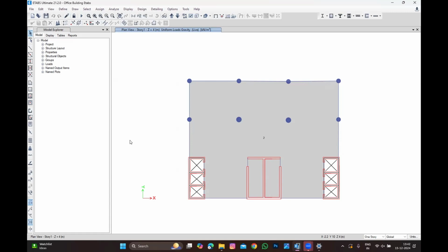Multiplied by what is the floor height actually? 3.6, right? Yeah. How much? 1.26, multiplied by 10 to 15% extra, 10% only. Mullions, transoms and mullions supporting the aluminum structure, 10% extra. Multiply by 1.1. How much?